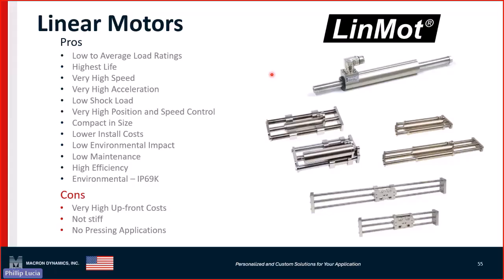Super efficient. They also are environmentally one of the best technologies for the most harsh environment. So say IP69K, wash down, steam, caustics. They have IPs up to the stainless steel versions up to IP69K that can accept all that. The cons is they're very expensive. They're the most expensive technology for pound of force. They're not stiff, and you can't really do pressing applications.